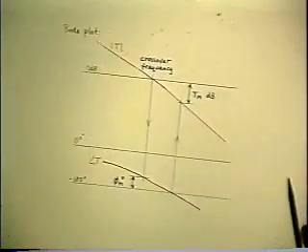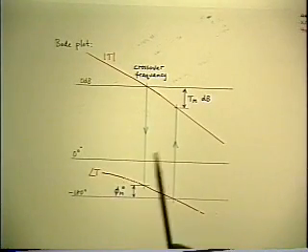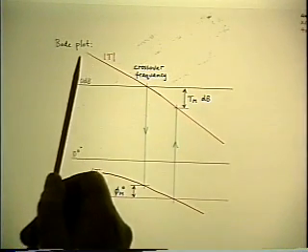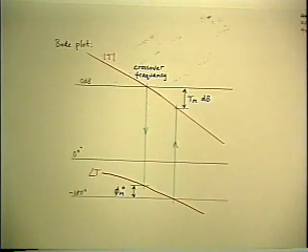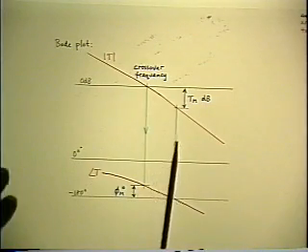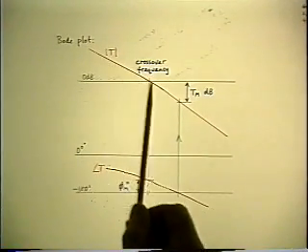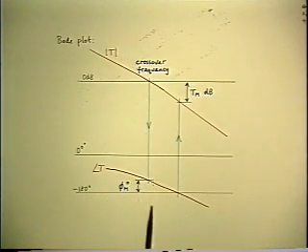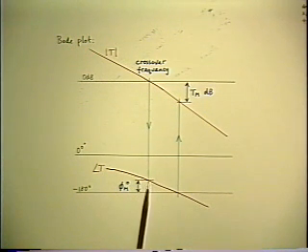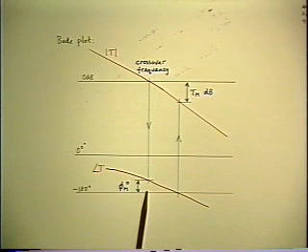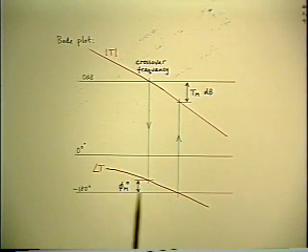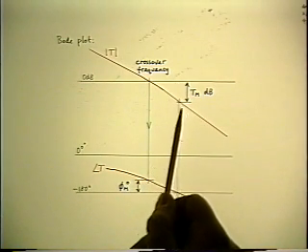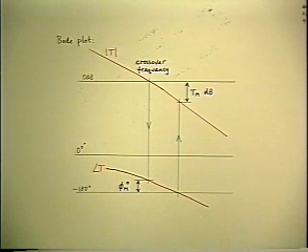And here's the same thing on the more conventional Bode plot, which is the plots we've been using all the time, which is separate graphs of magnitude and phase versus frequency. So here's the identification of those margins on this picture. You find the crossover frequency, which is where the magnitude is 1, and you look down to the phase graph, and how many degrees less than 180 it is is the phase margin. And then you find the frequency higher up where the phase may get to 180. And you look back at the magnitude graph, and how many dB below 0 it is is the gain margin.